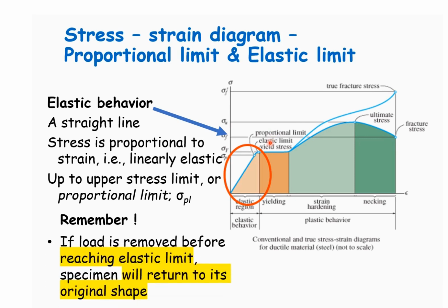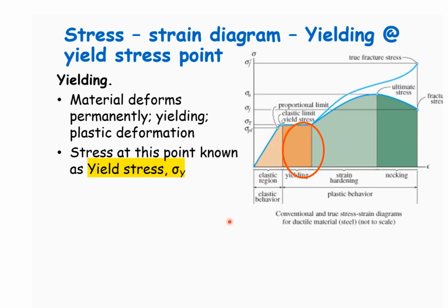This is the thing we have to remember for this phase within the elastic behavior, or elastic region: if the loading is removed before it reaches the elastic limit, for sure the specimen will return to its original shape. Next, we move on beyond the elastic limit.